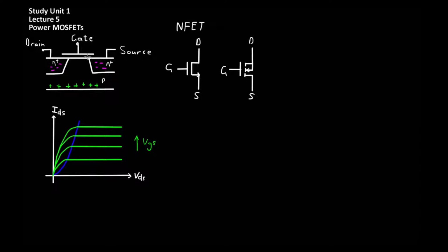This transistor, which is an NFET, uses n-doped regions on a p-type substrate. Fundamentally, the MOSFET works as follows. A positive voltage is applied to the gate. This causes a positive charge on the gate structure, which repels the positive charges in the p-type substrate away from the gate. This induces a channel underneath the gate, which is predominantly negative. This allows for negative carriers to pass from the n-doped regions, from the source to the drain.